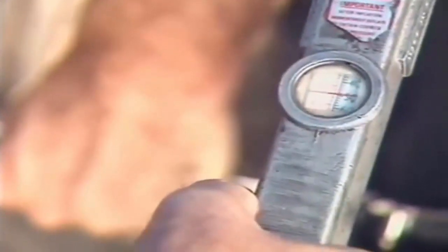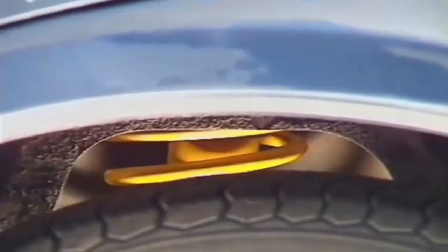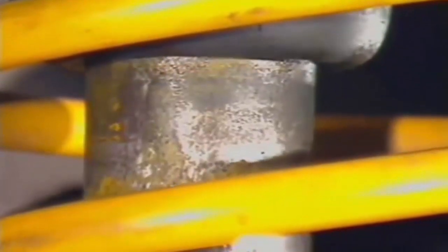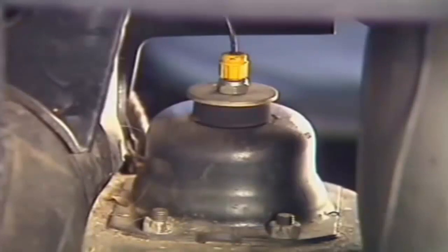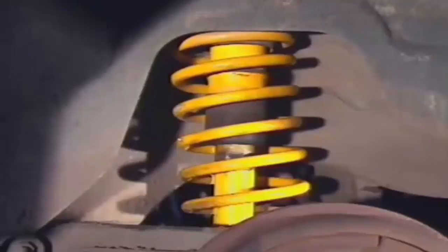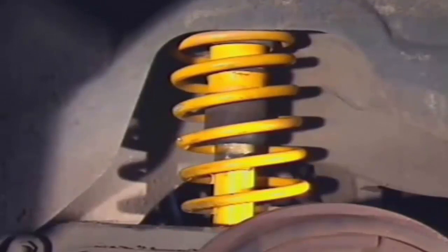By changing the air pressure in the cylinder, the ride height can be adjusted, as well as the stiffness of the suspension. Compressed air in the pneumatic cylinder can absorb smaller road shocks and provide better ride characteristics than just stiff springs alone. The rubber air cylinder is connected to a filling valve by a flexible plastic hose. Air from a tire pump or a hand unit forces more air into the rubber cylinder, allowing the suspension to support more weight.